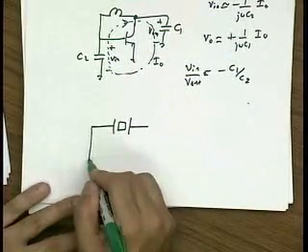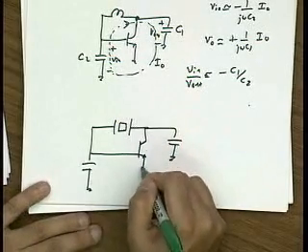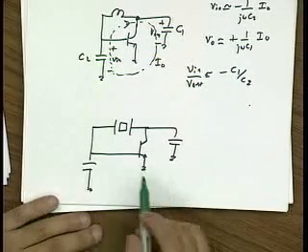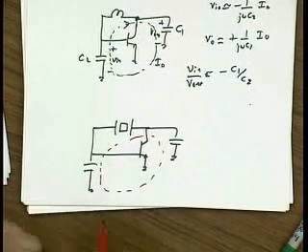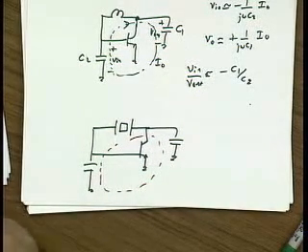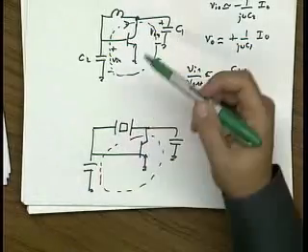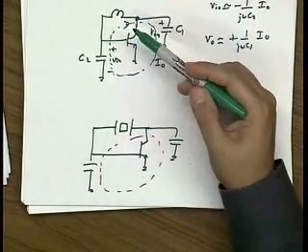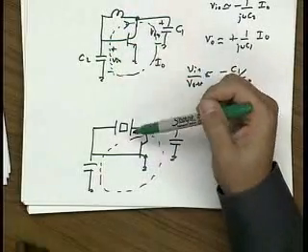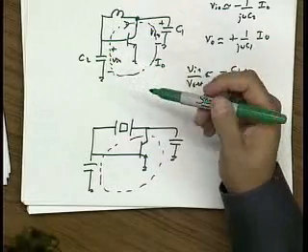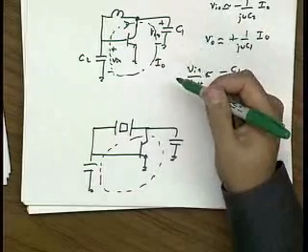I could take this same circuit and just replace the inductor with a crystal. And again, a resonant current will flow in this path, and it will oscillate just as you expect. The difference, though, is that the quality factor now is much better than you could achieve with an inductor. Okay? So I might have an on-chip inductor with a quality factor of 5 or 10. Go off-chip, I can get a more expensive inductor, maybe with a quality factor of 30 or 40. I use a crystal, I get a quality factor of 1,000,000. Right? You can't beat that.